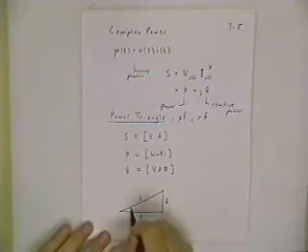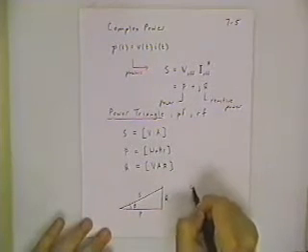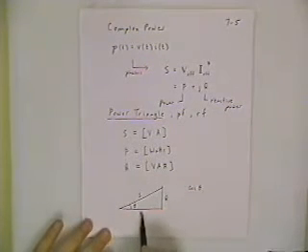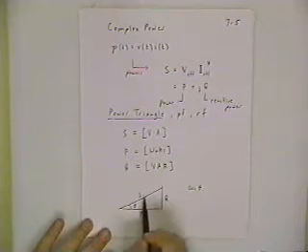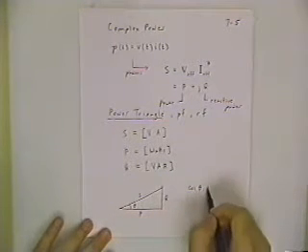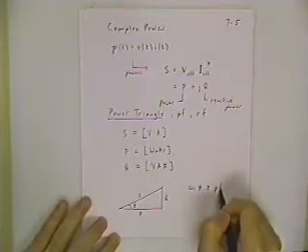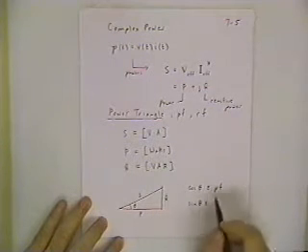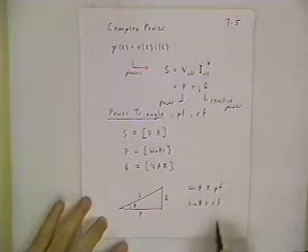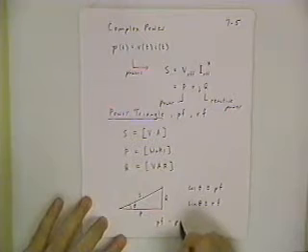Then there's an angle that comes in here, theta, such that the cosine of theta tells you about the relationship between the total power and the real power. The sine of theta tells you about the relationship between S and Q. So cosine theta is given a name of power factor, or PF. Sine of theta, since it has to do with reactive power, is given the term RF, or reactive factor. And the one that you're probably going to see most often in your exam questions is power factor.